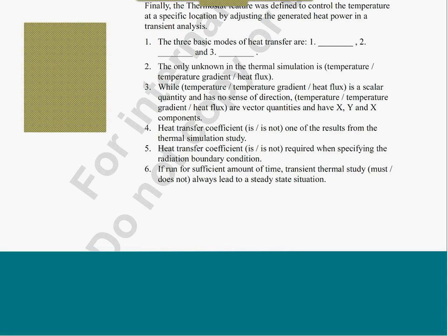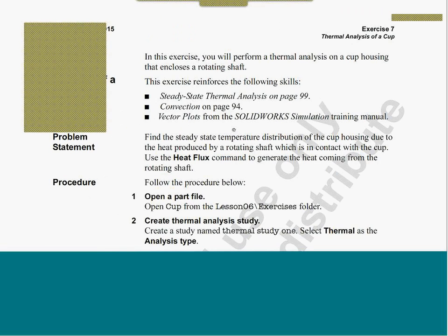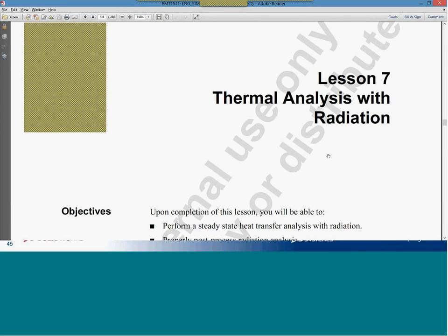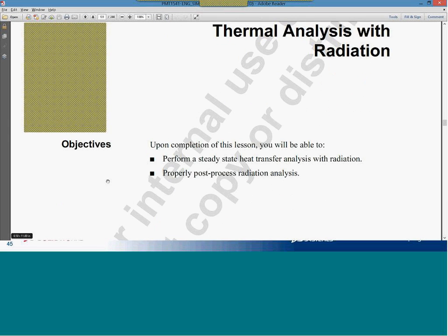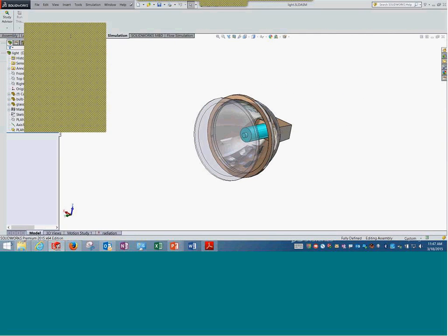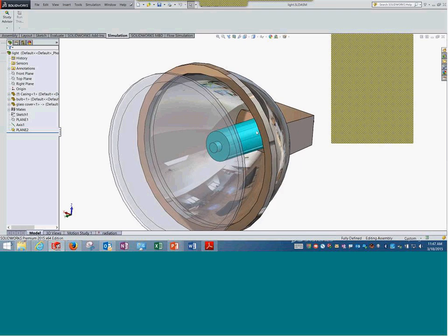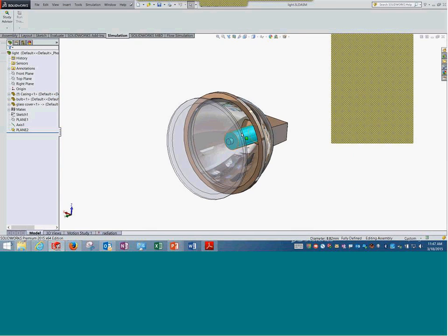Which of you are saying no. So let me go back. Let me scroll through this. So this simple example on thermal analysis, that's fine. Now the analysis with radiation. Here the things change a little bit. Let me run this setup directly. There is a lamp here which is creating the heat. Luminosity with view factor, fantastic. You are right. For radiation we need only temperature, emissivity and view factor. Perfect. So what is different in case of radiation?